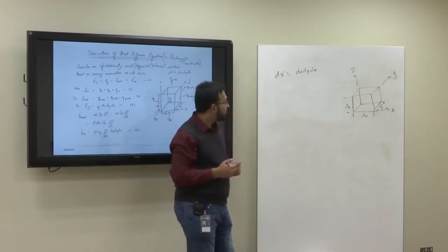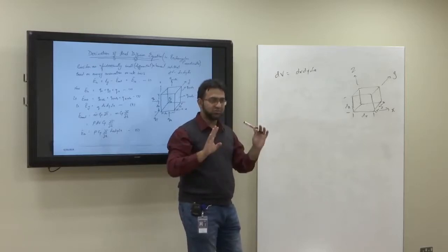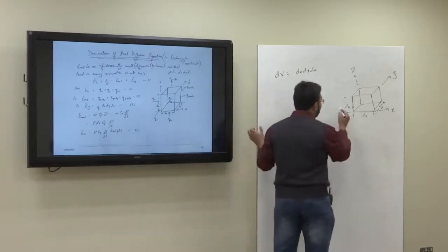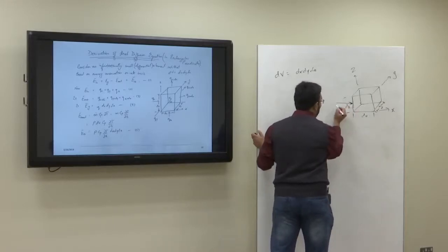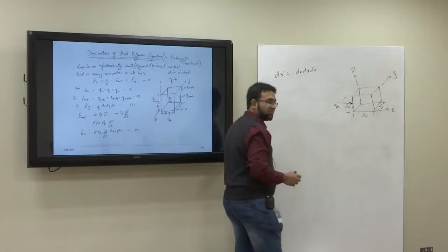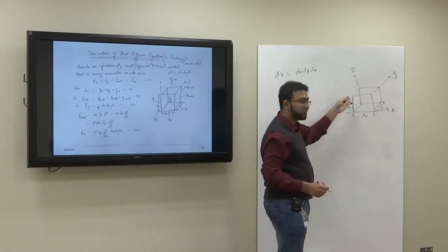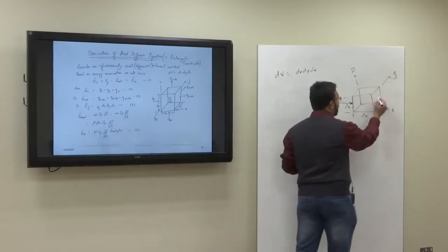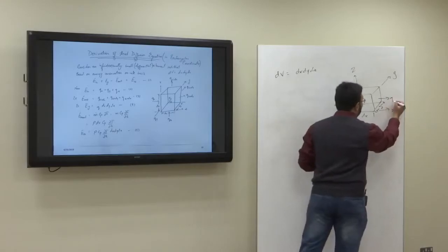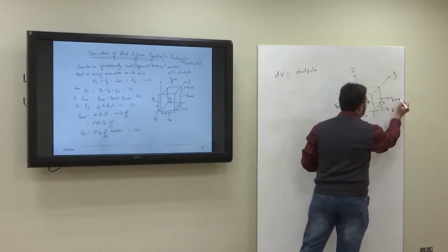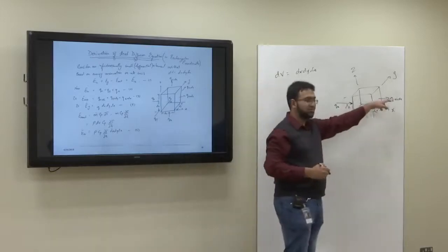Now what we assume is that heat is passing through the cube in all directions. So we have heat entering from this face, and we can call it qx. It's the heat entering in the x direction. If the heat is entering in the x direction from this face, then the heat will be leaving from this face, and it will be qx+dx, after a distance dx.